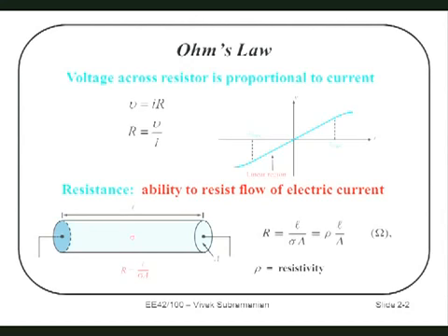So the follow-up to my first question: the reason it's easier for the electron to go out the other end is because it's heading in that direction already, right? No, that is one reason, but that's sort of underlying. That's a consequence, really, not a reason. The reason it's easier for the electron to go from here and exit here is the energy required to exit here. Because this contact is a good contact, it doesn't need that 4 eV it would require to exit here. In fact, what defines a good contact, it turns out, is something that doesn't need much energy to leave. So that's how we make good contacts.